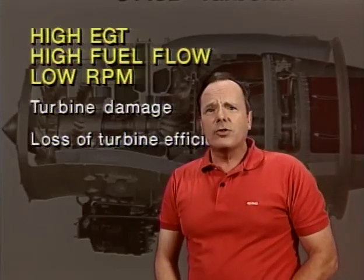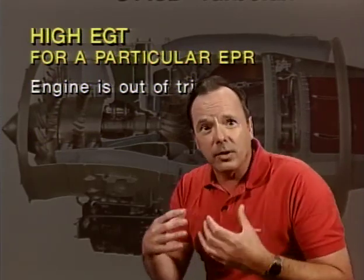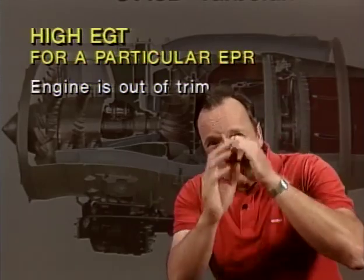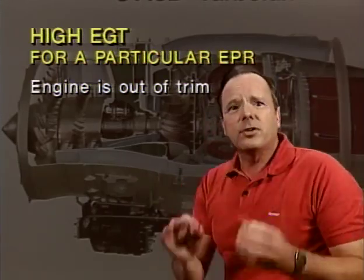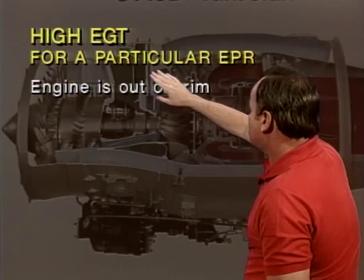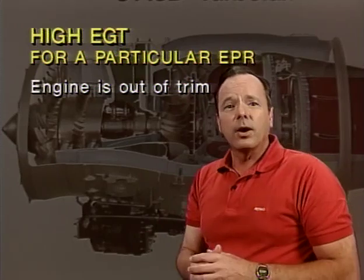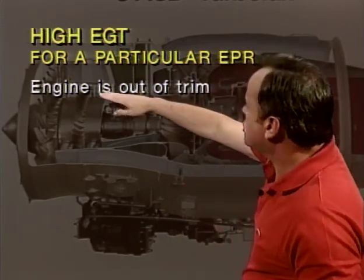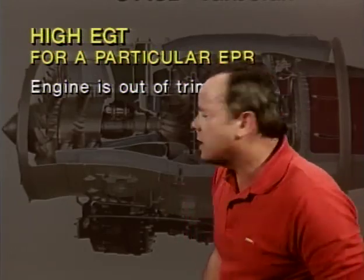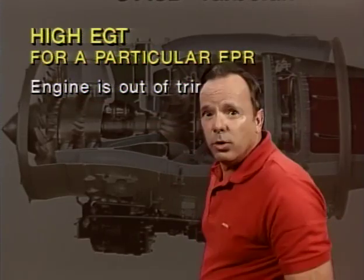Now let's assume that you have a turbine engine with a high exhaust gas temperature for a particular power setting, particular EPR. And let's assume, on the other hand, you check this engine over very carefully. You look at it with a borescope, you check it out, and you find out that there is no significant engine damage. So you have a high EGT for a particular EPR and you can't find any engine damage, now what would you check for? One of the things you would check for is, is the engine out of trim? And that means, is the engine fuel controller not adjusted properly? And that would be the thing to check under these circumstances. You trim the fuel controller of the engine.